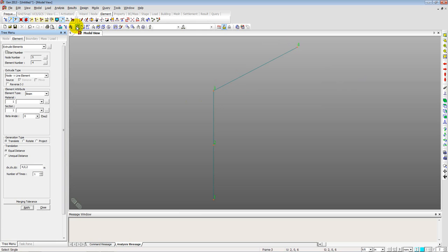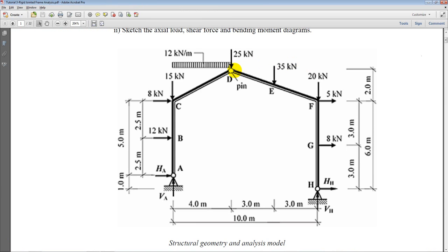Okay, now again select this node here. Let's see what distance we need to copy. That's 2 meter down and 3 meters 2 times in the x direction. So basically effectively we have 3 comma 0 comma 1 added 2 times.